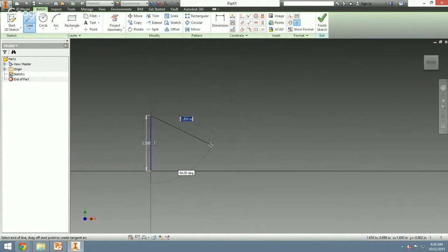All I did was zoom out a little bit. Okay, and I'm going to do the same thing this way. So 90 degrees again, type in 1.5, and good. 90 degrees, 0.75. And now notice I don't even need to click here. It automatically snaps to 0.75.